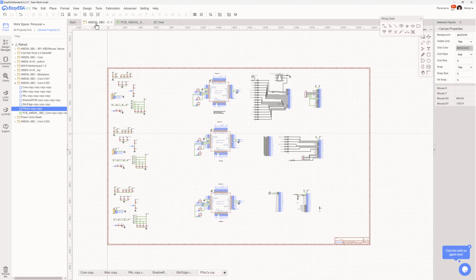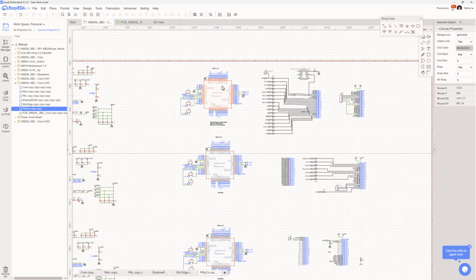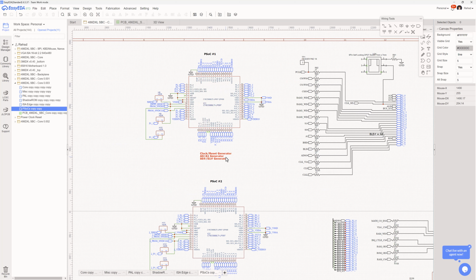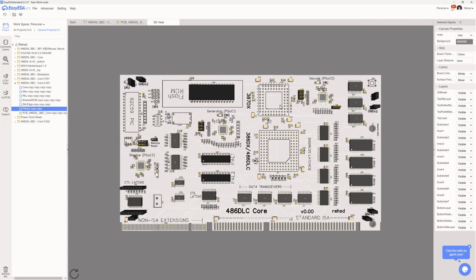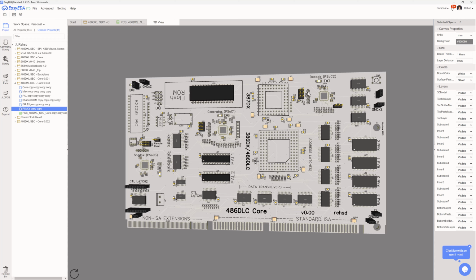So I took the parts of that I needed and put them into my actual schematic. If I come over to my schematic, I can see I've got three PSOCs, and I wired this up so that it will give me all the functionality I'm looking for and not load up all the extra components that I don't really need. Part of that is a pin header to do the programming. You'll see there's a PSOC and then a pin header. That's where I'll plug in my programmer, and I can update the PLD functionality of this PSOC, this PSOC, or this PSOC. They each have their header nearby.